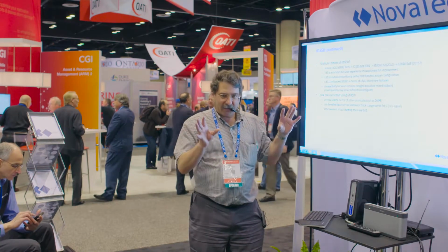Another application that you can start with in 61850 is a sample value system. The sample value system in 61850 typically uses a device called a merging unit, and I'll get into that a little bit later. But what it allows you to do is digitize the samples at the source and then use those digital samples elsewhere. And those digital samples, again, are broadcast out to all the devices that need them. Very interesting concept here, and there are some very good reasons to do this in terms of physics.